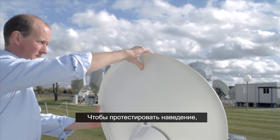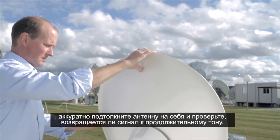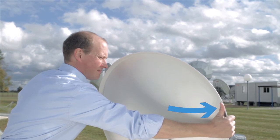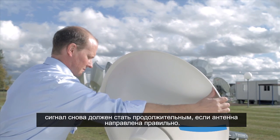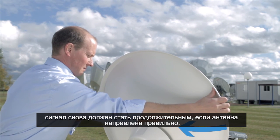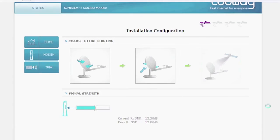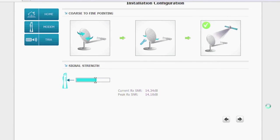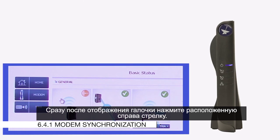To test the pointing, gently push and pull on the top of the antenna to see if it returns to the continuous tone. Then, push and pull on the sides of the antenna, and again, it should return to the continuous tone if it is pointed correctly. Once the pointing test is finished, you see a third box with a tick. Once you have a tick, you can click on the arrow on the right-hand side.